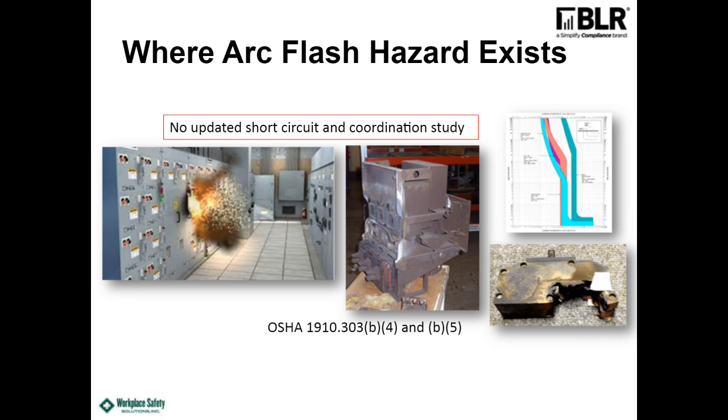The arc flash level is going to be much greater on the one in the middle. That's a 600 amp breaker. And if it's over-dutied, it may not operate in that time current curve, and it's going to cause a lot more arc flash hazard. And that's the problem with that.